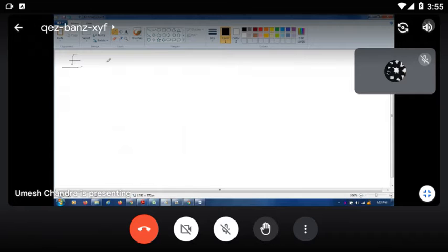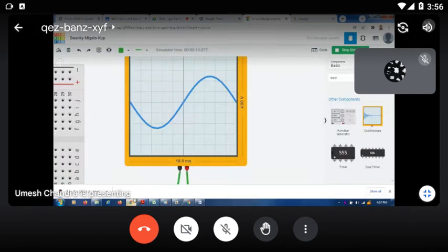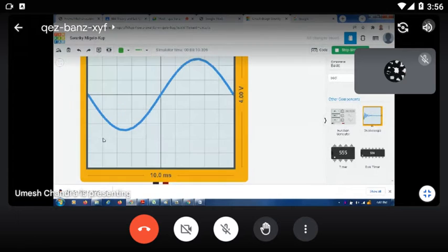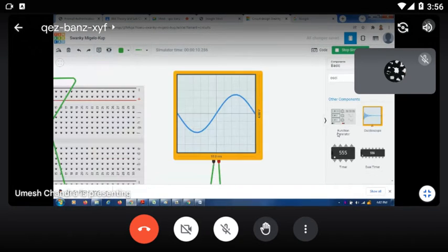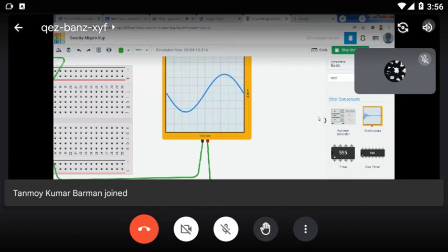Here this is frequency, this is V out and gain, that is A v. That is 20 log base 10 V out by V in. V in is always 2 volt. Okay. Then when 100 hertz, what is your output voltage? 2 volt. Then 200 hertz, what is your output voltage? You calculate only the output.